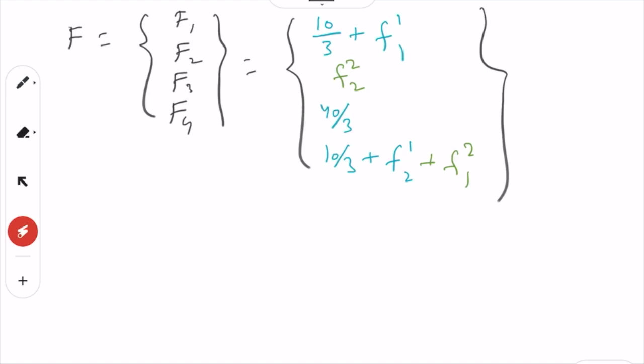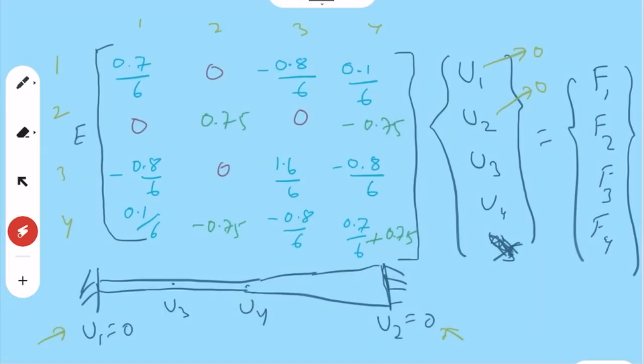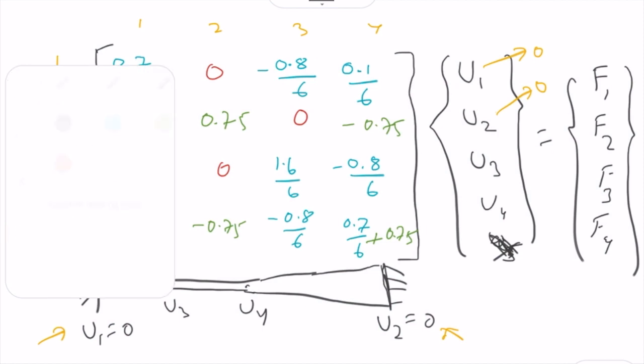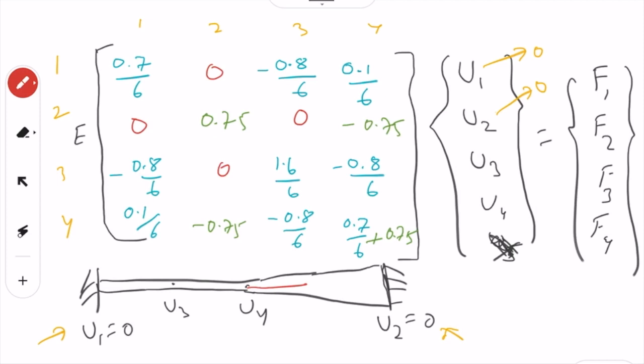So we are missing one thing. So far we have not implemented one thing, and that is that there is a force here, and the value of that force is 150 Newton. So this is P equal to 150 Newton. This we have not implemented, so this we have to add. Where? We have to add at node number 4. This is global node number 4, meaning the last row we have to add this P.